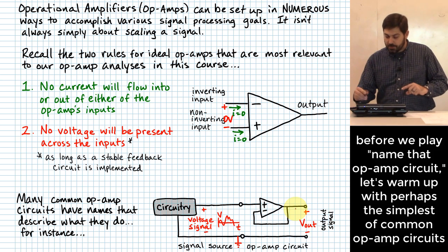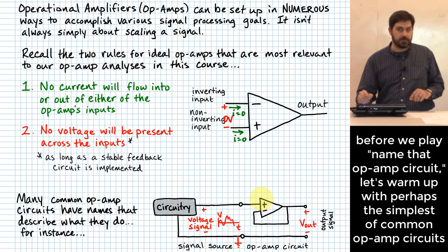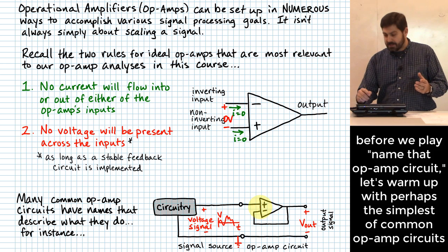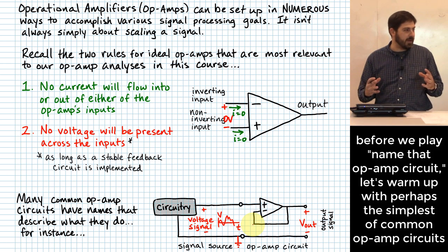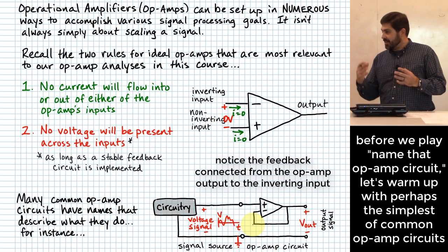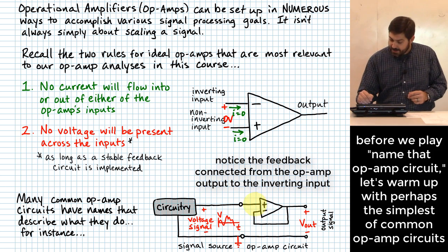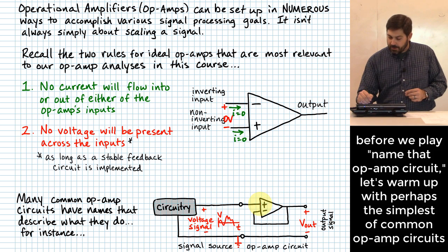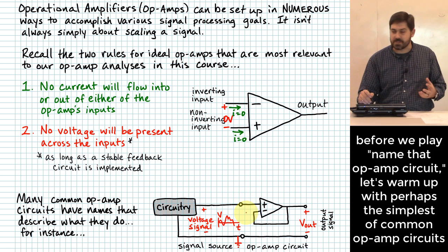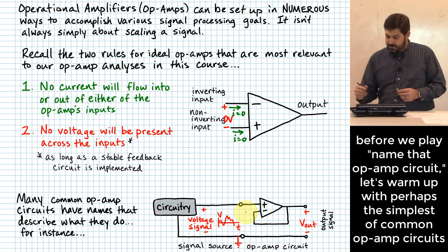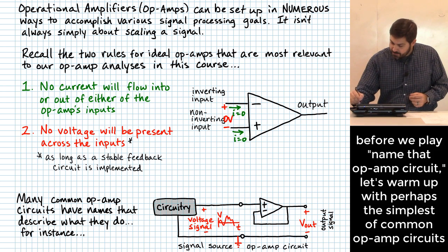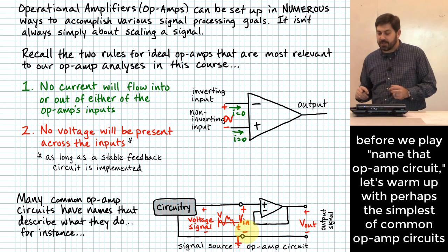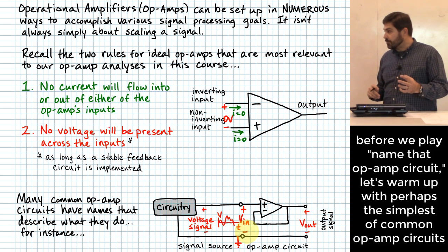What does that mean the voltage has to be on the non-inverting terminal? V out. Okay, assuming that this has a proper feedback loop on it, and it does, it is going to have V out on that non-inverting terminal. Well, what would you call that in terms of this circuitry that's pumping something into this circuit? I would call it something like maybe V in, right? That V in is this voltage that you're feeding into this thing in the first place.